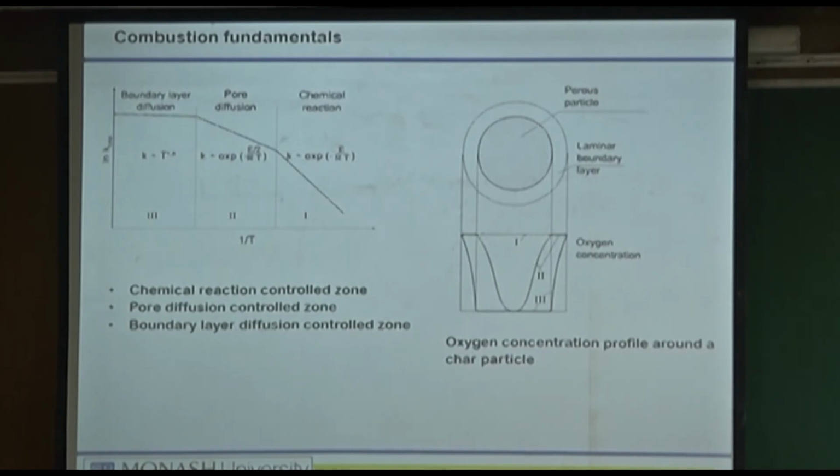But one other thing that happens, let me also make a point. You can have a high ash coal and a low ash coal. But the coal particle disintegrates very, very fast, even though it is going into the furnace between 10 and 100 micron. As I've shown there, they fragment as a consequence of thermal shock very, very quickly. So the discrete mineral particles go out this way, that way, and what remains accessible is predominantly the carbon to the oxygen. So that's where the high ash, low ash effects somewhat cancel out.